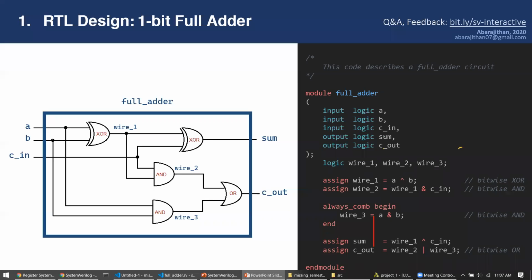First one is, is there a specific reason we use the 702 board? Is it a generic selection? I'm just using 702 because I have used it before. You can use whatever board you have. Usually your own university will have a lot of FPGA boards for you to borrow and use, because the boards are expensive, costing around 80,000 to 1 lakh. So always borrow a board from the university. Then you can select that particular board. If it is a Xilinx board, you can select it in Vivado. I'm using 702 because I already have used it.